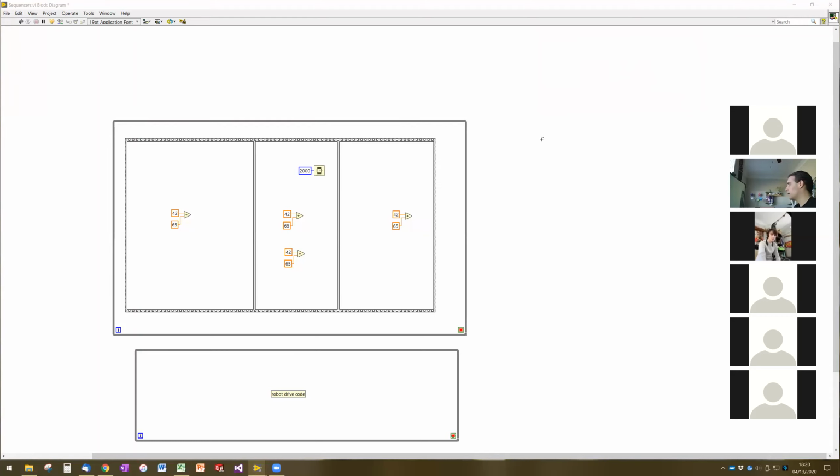And so what we can do is create a timer just like that, where one of the events that happens is we start the timer, and then we don't move on to the next event until the time since the timer has started exceeds a certain amount. But we can keep looping because the clock's going to keep running. So we can cycle around and continue doing all of our other operations while the timer's running. It's no longer a wait for, it's a check to see if the timer has exceeded that certain amount of time.